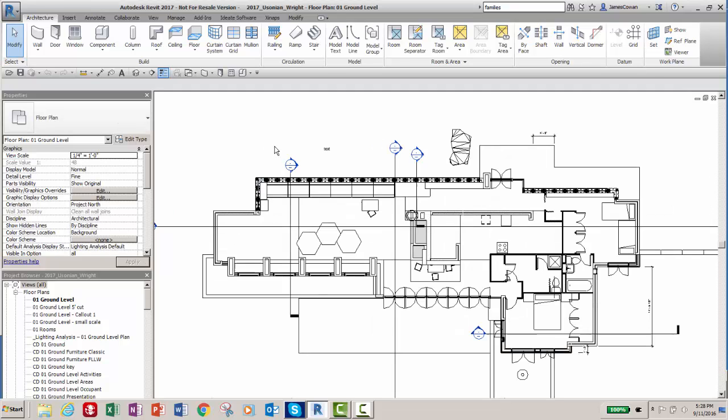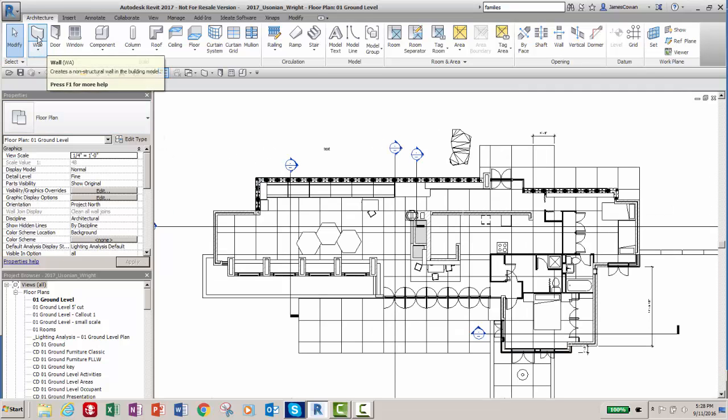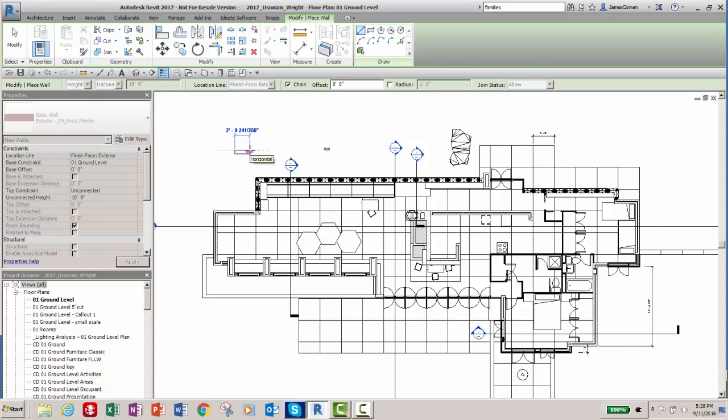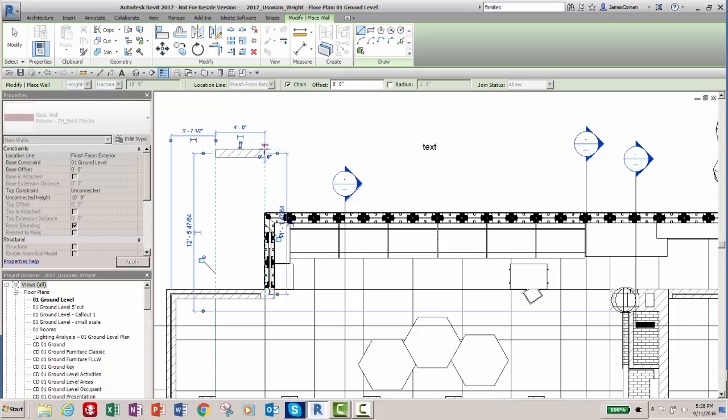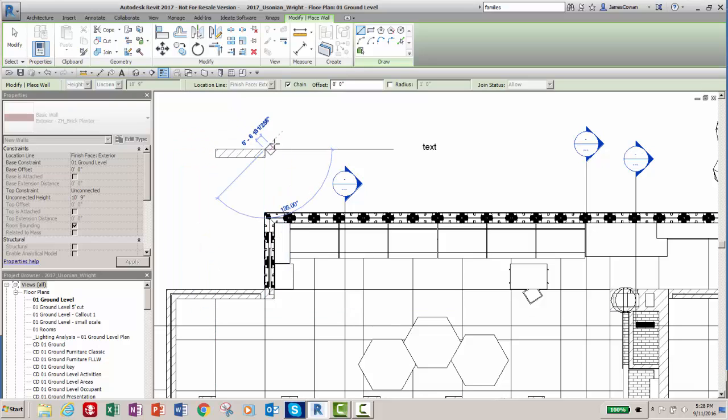The way that's supposed to work is if you're drawing something, like say you're drawing a wall, that the zoom factor affects kind of snapping of your project. So I don't know if you can see that. As I move my cursor, I set it to 4 feet, so as I move my cursor, at a certain point, it snaps to 4 feet. And if I continued, and the other one I set was 45 degrees, so you see how I can go up at 45 degrees, and again, it's going to snap when I get to 4 feet.